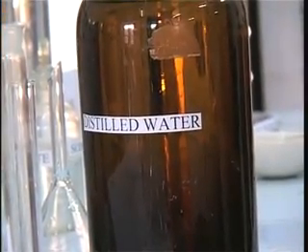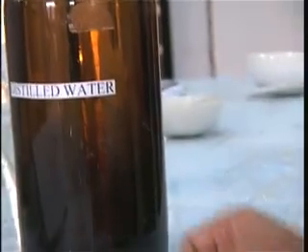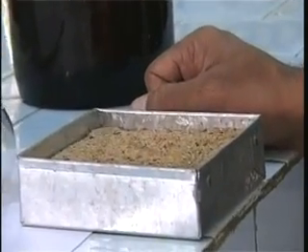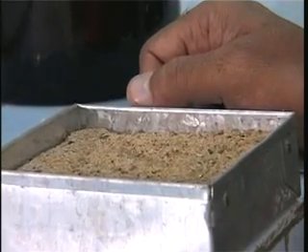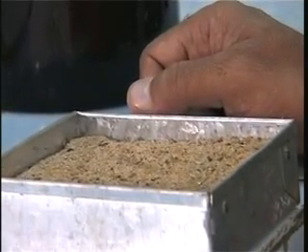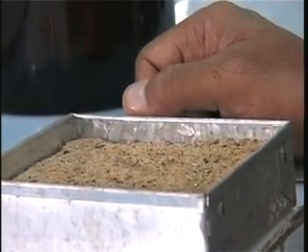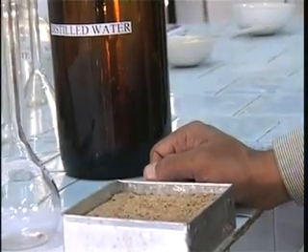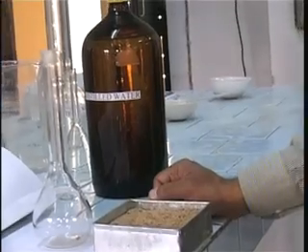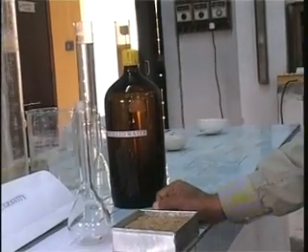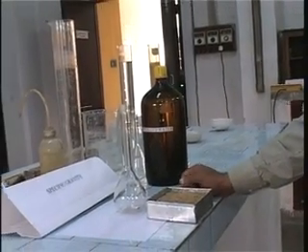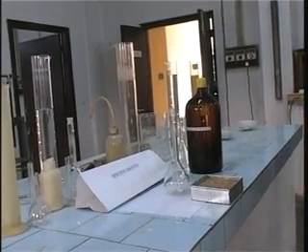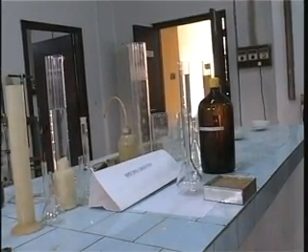We are going to take a representative amount of soil in the flask, and then we are going to top it off with distilled water up to the mark that we saw there on the stem of this flask, and we are going to keep it under suction to de-air the water so that there is no bubble of air included in between individual grains of the soil, because that is going to introduce some error in the reading.